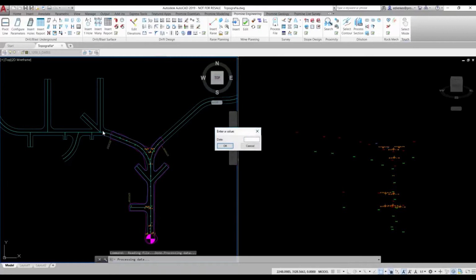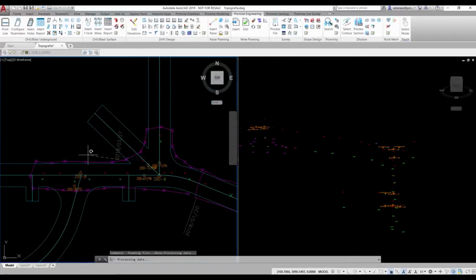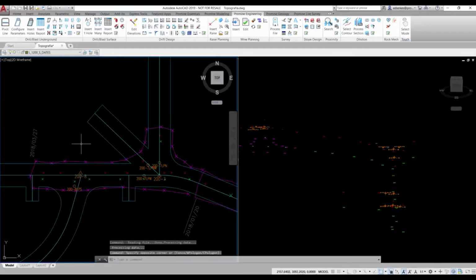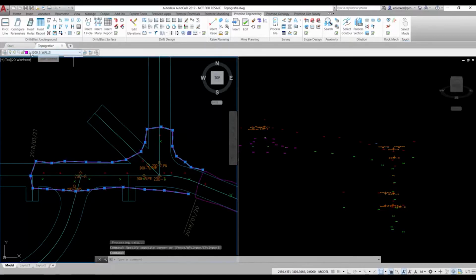with OK. We're quickly inserting the date of the survey, and now we can see the newly added survey points in the drawing. With this new part, we can see that the different types of points were already sorted into distinct layers, and based on their types are represented by different pre-configured blocks.